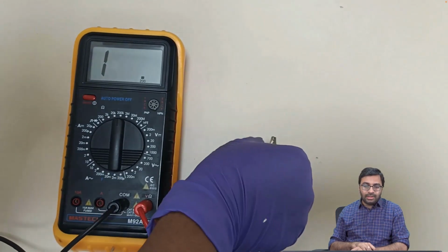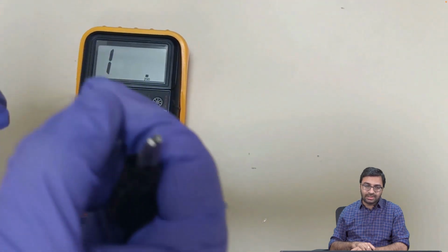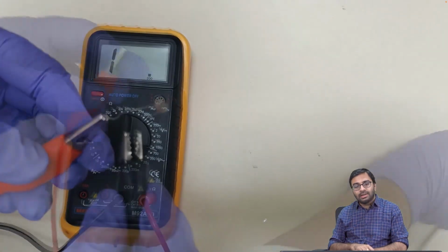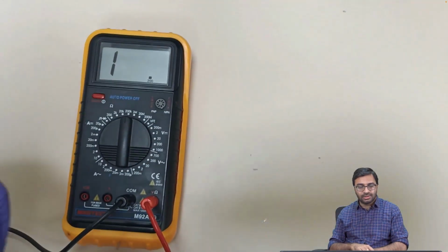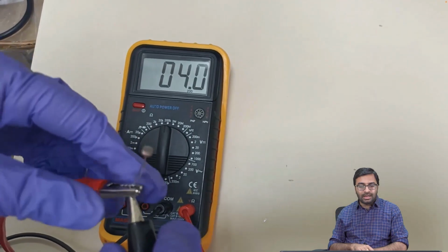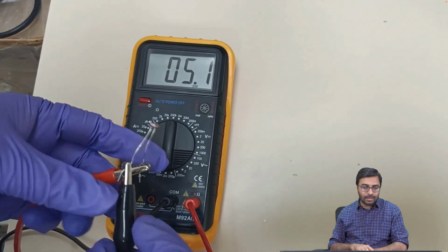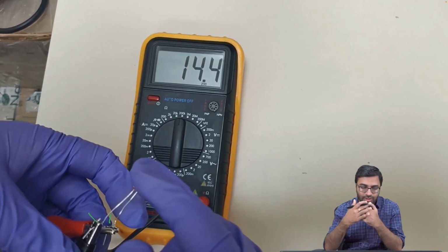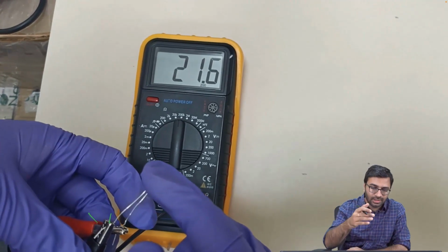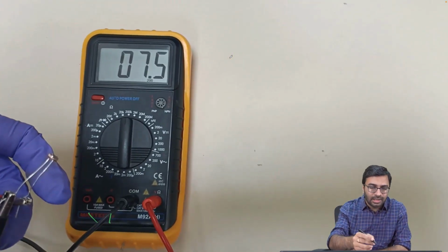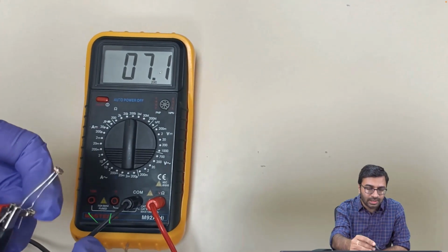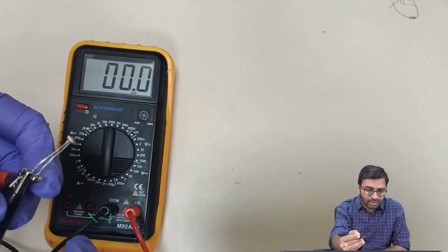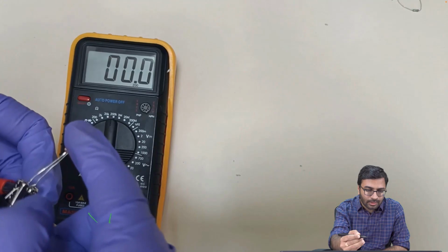Again, we have performed a very basic experiment with the sensor. We connected the sensor with a multimeter, and the moment you connect it, it shows the resistance in that lighted condition. So that is how you connect it. Now if these are connected, make sure these two terminals are not touched. Okay, if they are touched, then you'll see a zero resistance. However, here you can see when it is in the lighted condition, it is giving a resistance value which is very high.